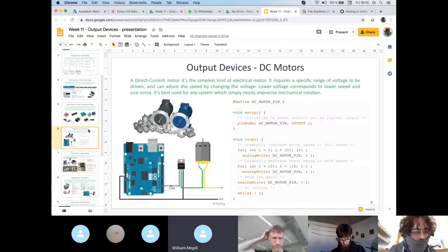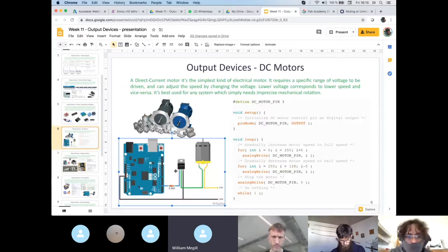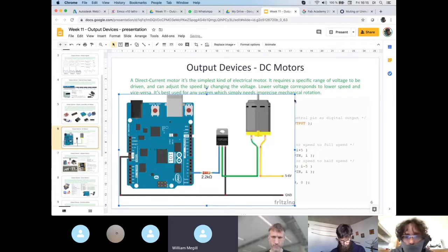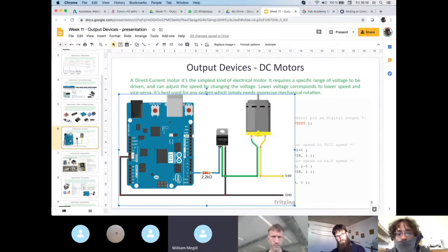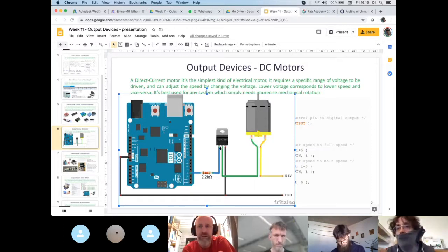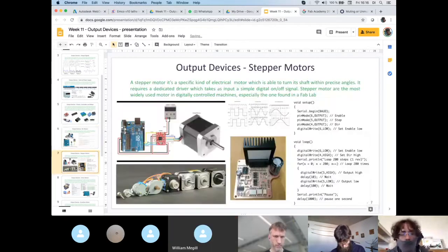Sorry, the resistor we have here, the 2.2 kilo ohm resistor, can't we use the internal pull-up resistor arrangement in the board? You cannot. This is something different because, as you can see, this one is not connected to VCC or ground. It's connected to the gate. Got it. It's just for changing the gate voltage, because maybe this transistor works from 0.5 to 3 volts instead of from 0 to 5. So you need to change the voltage, depending on the transistor you have.